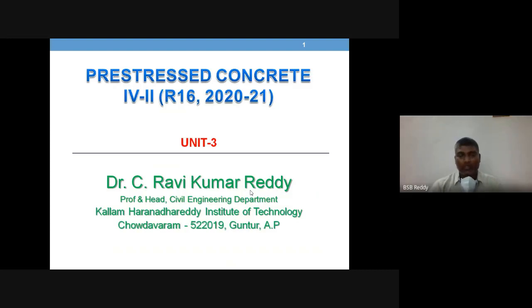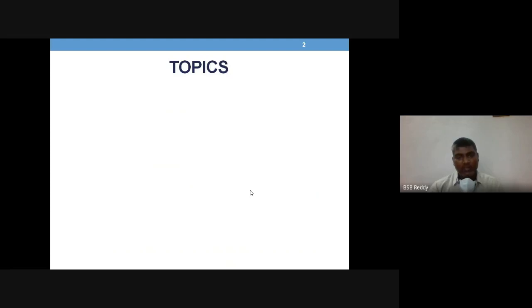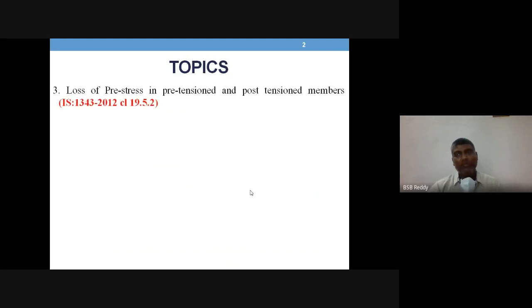Now let us talk about Unit 3 of your syllabus, where the whole Unit 3 content is about loss of pre-stress, which means you are going to induce some pre-stress value through the tendon to the concrete. What exactly you have to concentrate on is the effective value of stress available finally in the concrete.